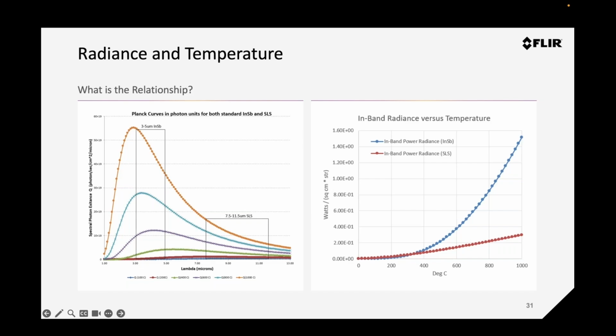In the midwave, there's more thermal contrast, and certain phenomena can only be seen in this band. It also sees farther through humid air, and it has less expensive cameras and lenses than cooled long-wave SLS. It also has higher QE relative to typical long-wave SLS detectors.